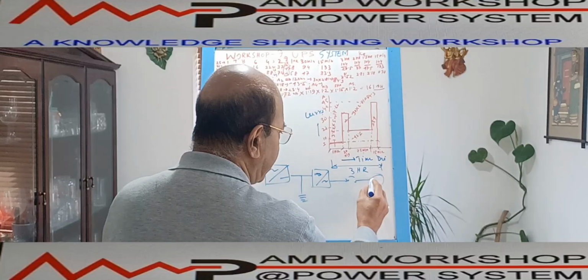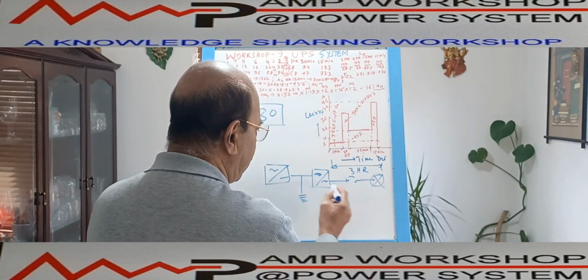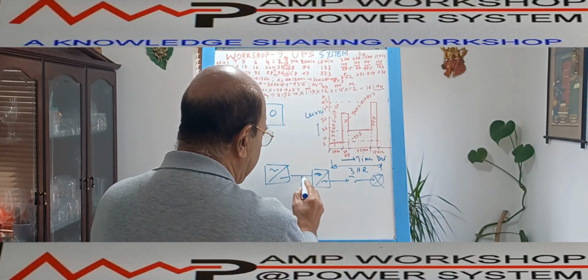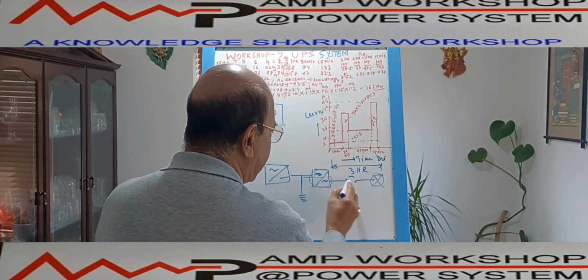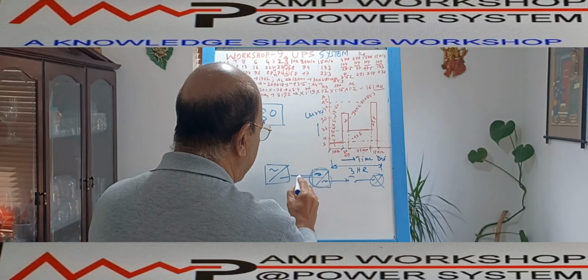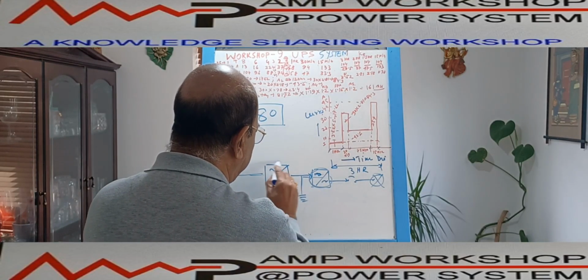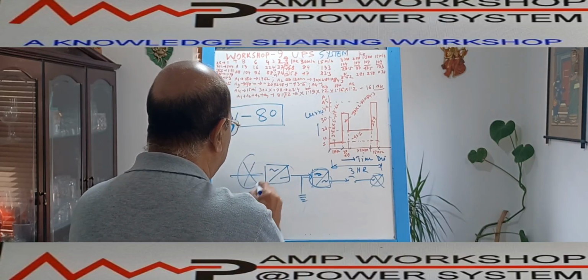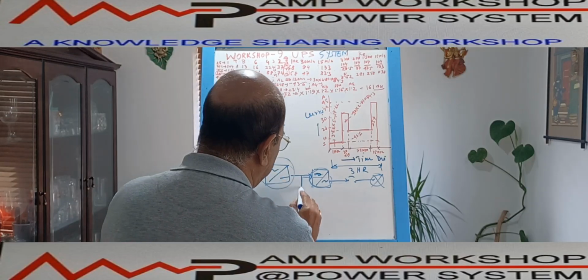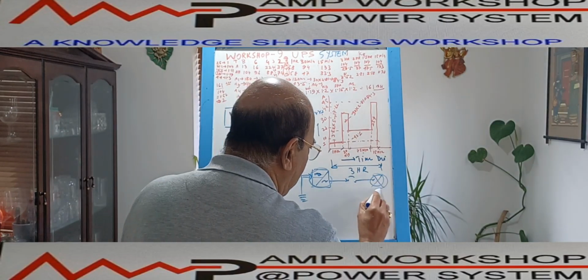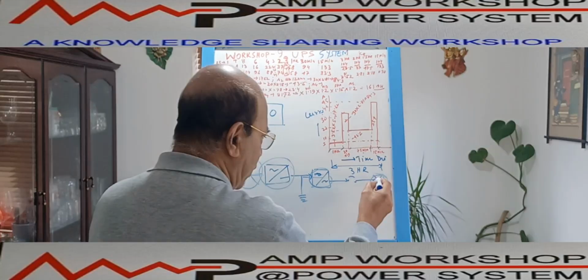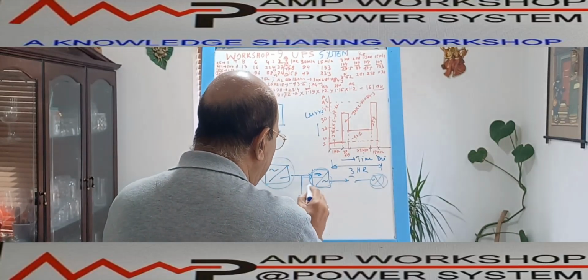The moment the AC load changes, increased or decreased, automatically the inverter has to cater that amount of current. The inverter is getting what? DC input current. Normally DC input current comes from the converter, but when the power supply is not available, the converter is not working, so the battery has to discharge. When the load is more, you need more input current.